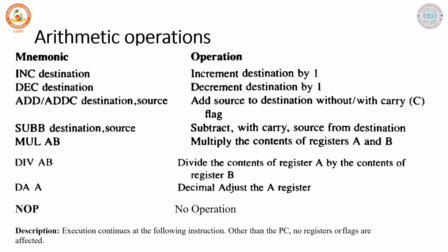The flags are used to know the status of the carry generated or any flow control of the particular program. Say for example, I'll just take an example of a subtraction. In case of a subtract operation, we may produce a positive number, or the result may even be a negative number. So based on the number being positive, a certain section of your user program needs to be executed.